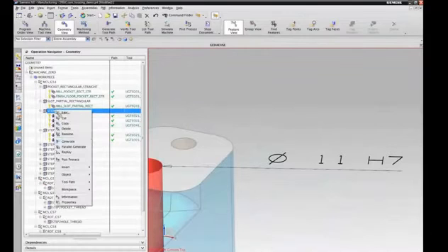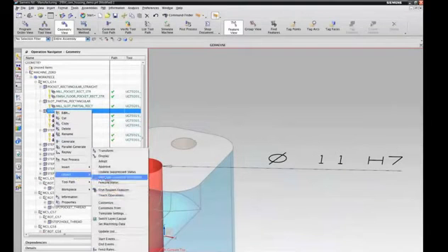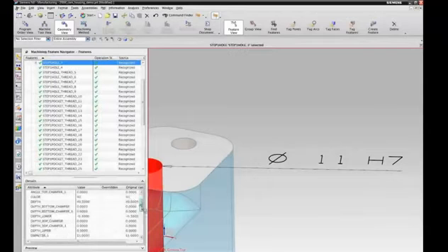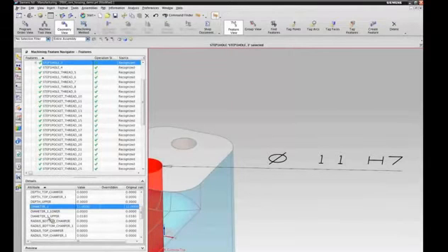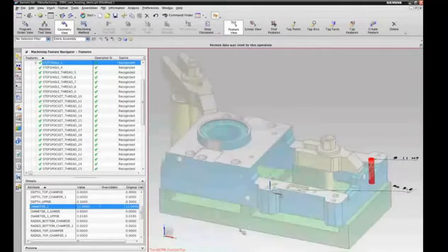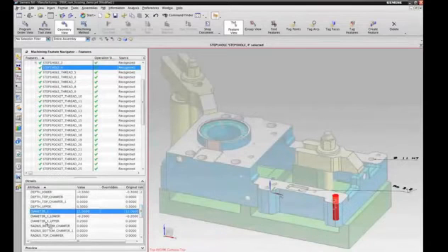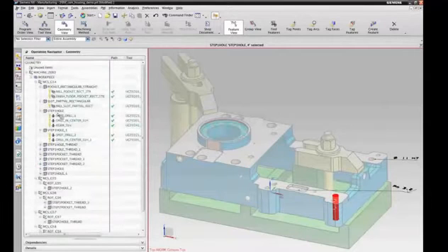So if I go back to my object, find related features, to my feature, look at the details, then this actually has a diameter tolerance. The diameter is 11 mil, but it has a lower tolerance of 0 and an upper tolerance of 18 thousandths of a millimeter, so it's a very accurate hole. If we look at the other one, that is probably that one, it doesn't have that tolerance, same diameter, but plus minus 0.2, obviously resulting in completely different operations.